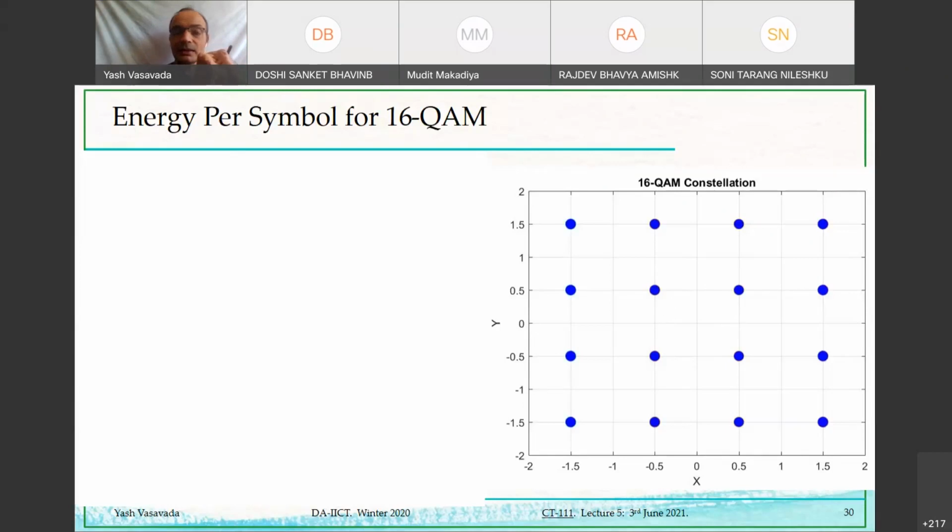But what is the price that is paid if we go with that approach? Performance decreases. Yes, and that performance decreases. But why is that? Why do you think performance decreases? Probability of error increases. The boundary is very close to the symbol. The distance between symbols decreases, so the error in decoding will increase. The correct detection region decreases.